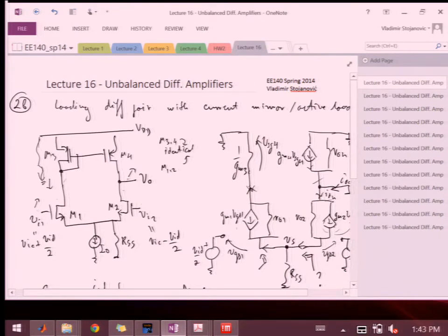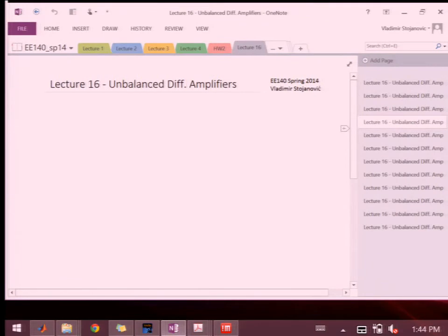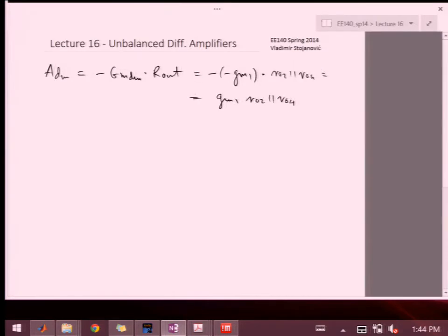So then these two are in phase. Right? Another way to think about it is always between gate and drain, there's always a pi phase shift. So I get pi, and another pi is 2 pi. And then between this gate and this drain, I get pi. So if I'm defining my input as VI1 minus VI2, then my total gain has to be positive, the way I've organized the circuit. Okay? So this is just a useful thing to always keep in mind when you're checking the calculations, because I may have gotten my signs wrong. Okay, so this is the differential mode.